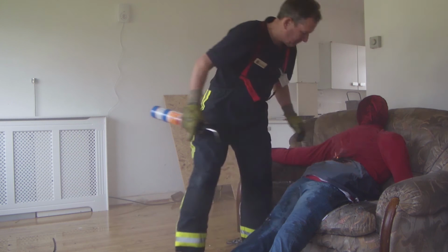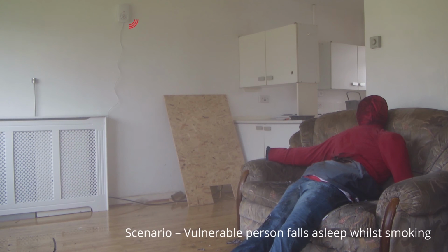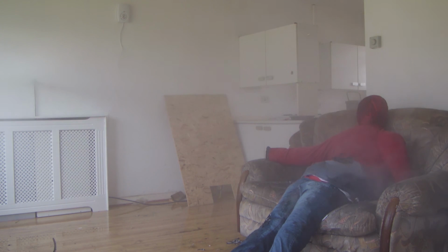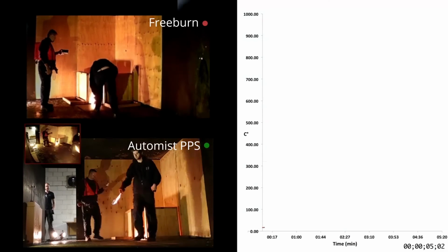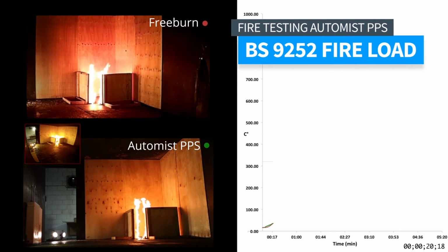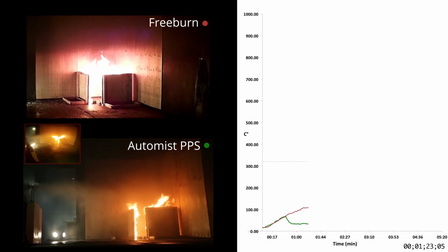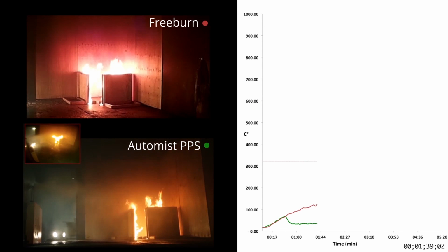So we have here a little test where the clothing on an individual is being ignited. The flame detector has picked that up, and what is going to occur when that picks that up is the first thing that occurs is an audible message that essentially says, put out the fire, put out the flame, and if you don't, it starts a countdown, and the system will discharge, and then the system fires and controls the event.